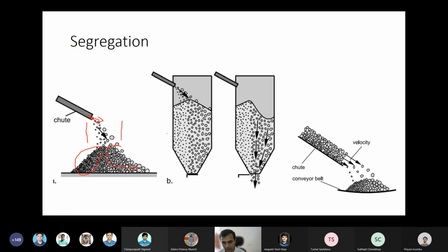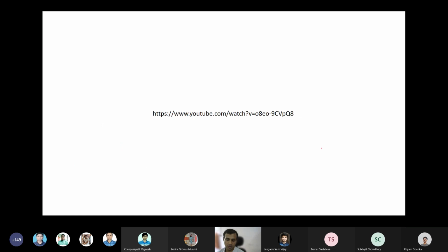And this is on a normal plate. You will see the same phenomenon in the silos also. Either the discharge can be dominated by this or by this. Whichever particles come first to the discharge below will dominate, so obviously the other zone becomes stagnant. Then all types of flow problems can take place. Similarly, the particles coming out from a conveyor belt can also segregate depending on this.